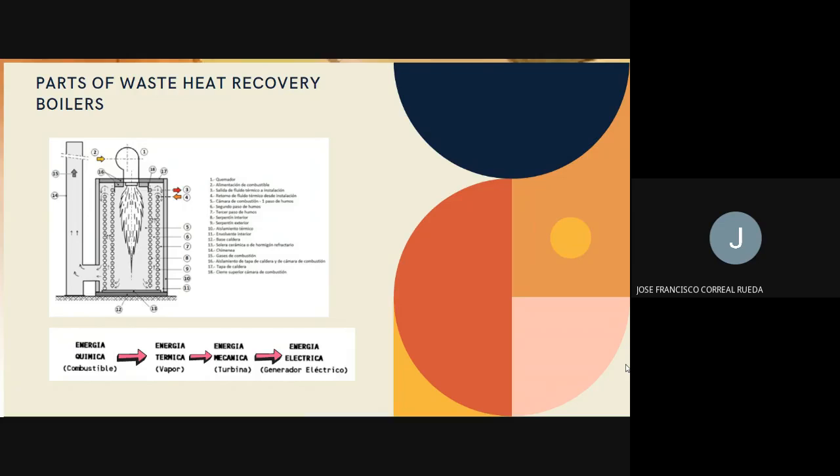The hot gases transfer their heat first to the superheater tubes, then to the bank of steam generator tubes, and finally, in residual form, to the economizer tubes before going out to the atmosphere. The feed water circulates through the economizer, where it is heated before entering the steam dome. The water goes down the downcomers, the cold side, toward the lower dome. Then water rises through the risers, the hot tubes, to the steam dome.